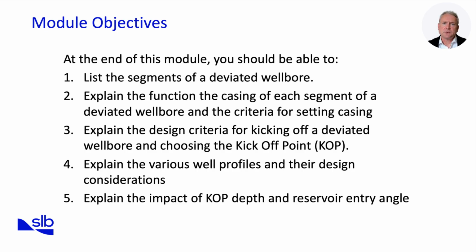A deeper kickoff point may save surface distance, but introduce high doglegs and mechanical stress. Likewise, J-type versus S-type trajectories represent compromises between displacement, zonal isolation, and cementing effectiveness. By the end, you should be able to rationalize well path selection not only mathematically but also operationally, making plans that balance drilling efficiency with reservoir and completion requirements.